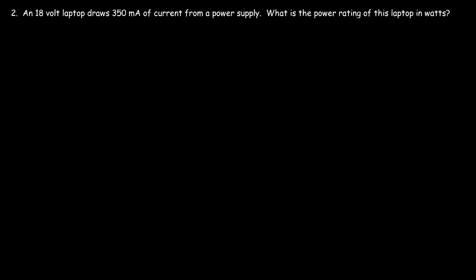Now let's move on to number 2. An 18-volt laptop draws 350 milliamps of current from a power supply. What is the power rating of this laptop in watts? Feel free to pause the video if you want to try this problem. So in this problem, we could simply use this equation. P is equal to VI.